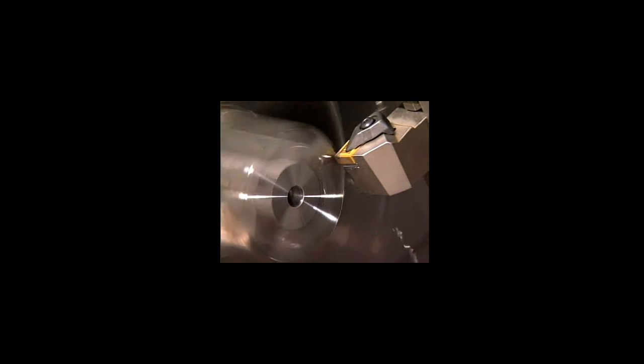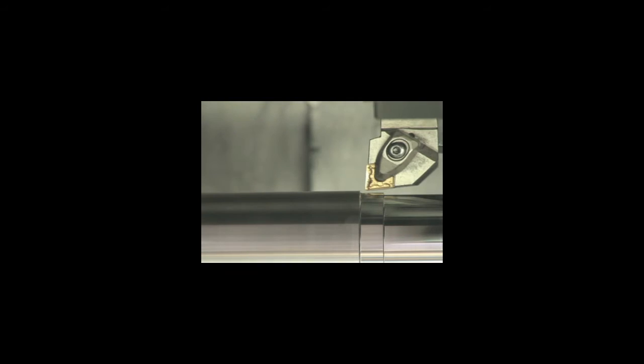Here is an example of facing where the tool must have high toughness. This part has a number of sharp edges, and each time that the tool comes in contact with an edge, there is a shock load. In each rotation of the part, the tool gets hit 4 times. This is a finished turning operation with no interrupted cuts. The tool does not require high toughness but needs high hardness and wear resistance, so that it can retain its cutting edge for a long time and produce parts accurately within tolerance.